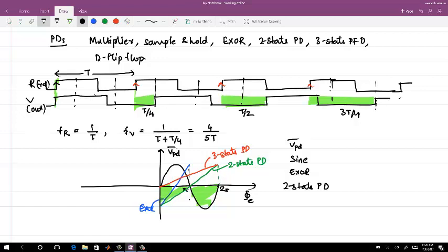If the phase error detector output is this, and you're just integrating to get the frequency error, can you confidently say that the DC value will be positive? It can be positive or negative depending. Sometimes you're increasing the frequency, sometimes decreasing the frequency, even when you have to increase the frequency always.